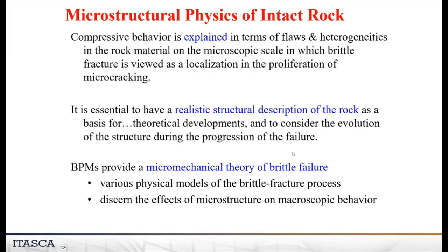And so we're arguing that if you build a bonded particle model in an intelligent way, it allows you to explore the fundamental behavior of how rock-like materials behave. That bottom one: how does the microstructure affect the behavior of the rock? And we have an amazingly rich microstructure that we can build. We can build a huge number of different microstructures with this approach, okay?